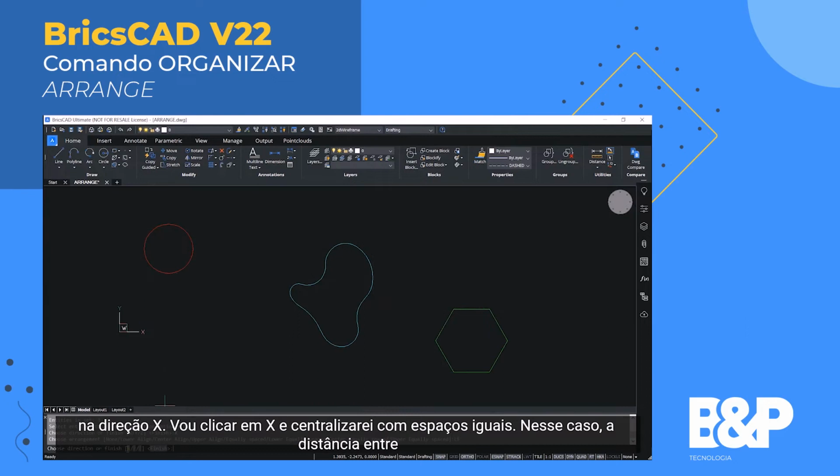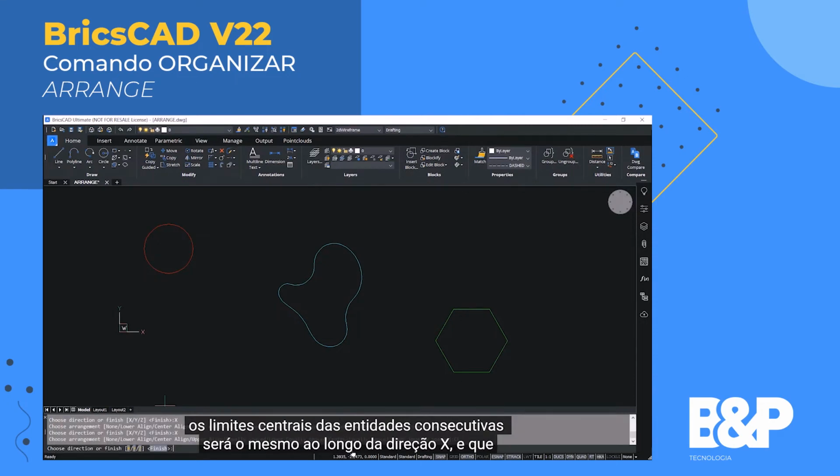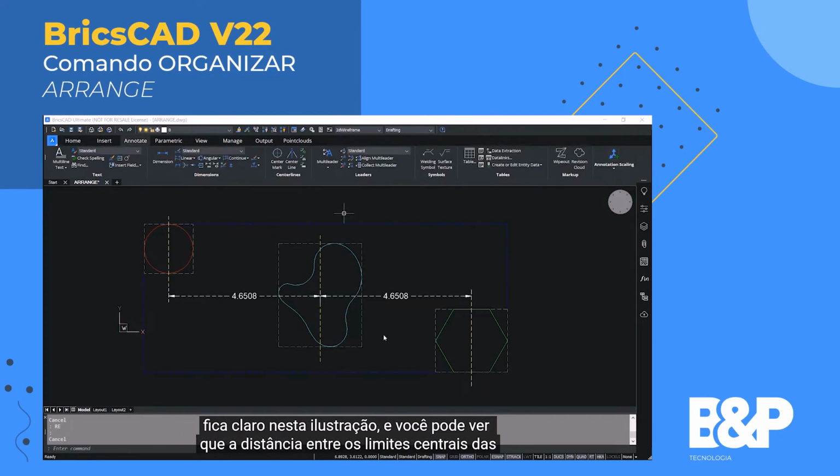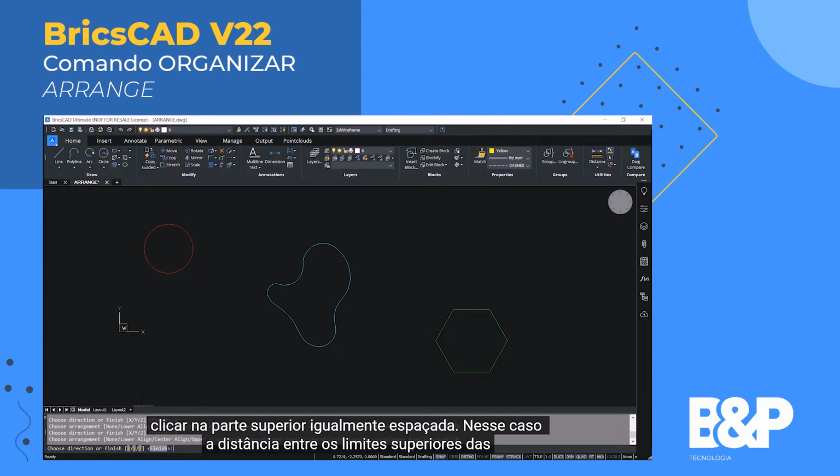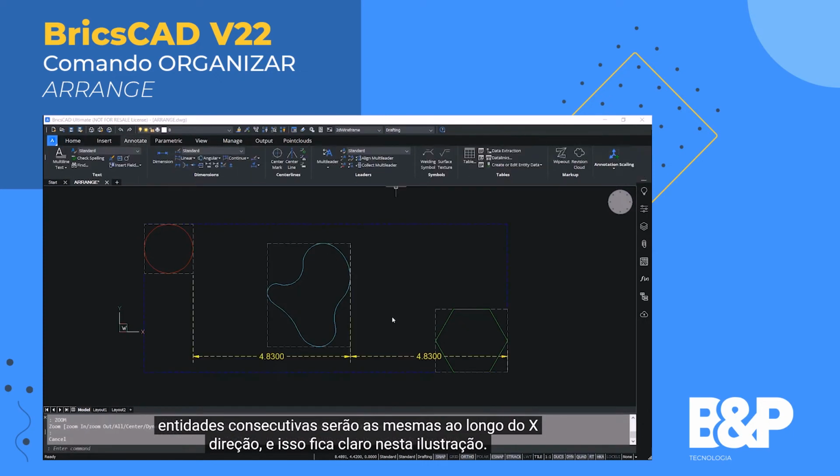I'll click on X and center equally spaced. In this case, the distance between the center bounds of the consecutive entities will be the same along the x direction. And that is clear from this illustration. And you can see that the distance between the center bounds of the consecutive entities are the same in the x direction. I'll click on x again, then I'll click on upper equally spaced. In this case, the distance between the upper bounds of the consecutive entities will be the same along the x direction. And that is clear from this illustration.